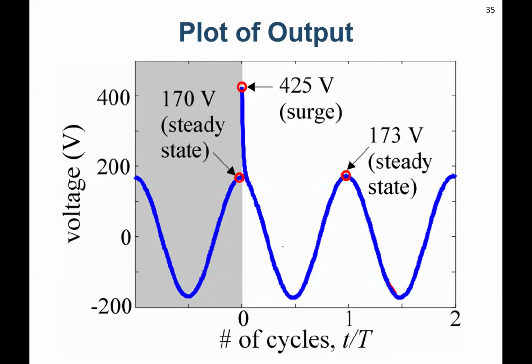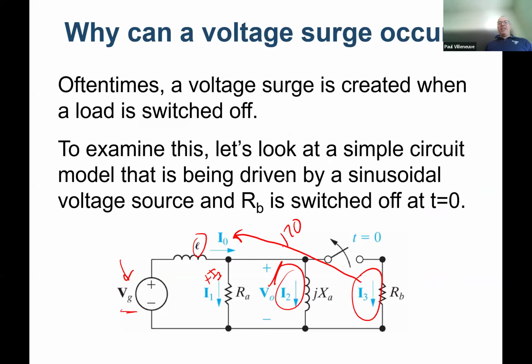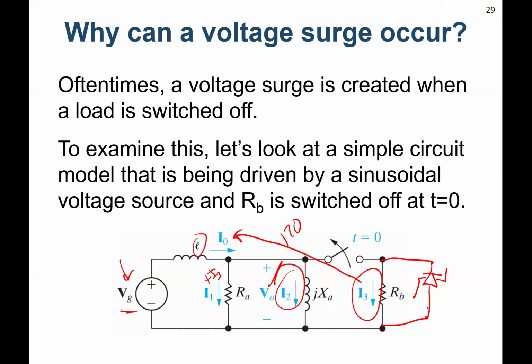Oh, I bet. The whole home surge protector is a big capacitor, isn't it? No. Okay, great question. If I wanted to modify the circuit and protect it from surges, normally what you do is use a Zener diode. A Zener diode, right? You'd have to have it in both directions, because it's AC. Exactly.